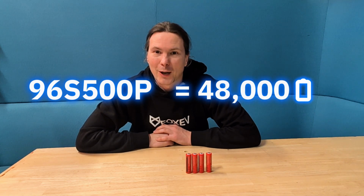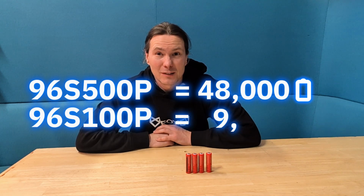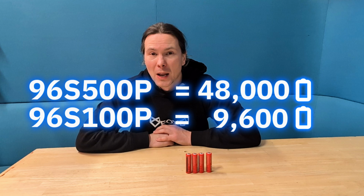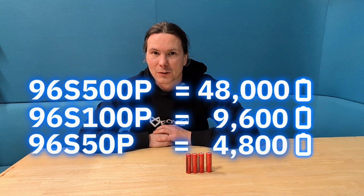400 volts, the motor, we also need to get to the 400 volts, so we need to put some of these batteries in series. So let's put 96 of these in series. So that gives us this notation here. 96S, 500P, that's 48,000 battery cells. 96S, 100P, that's 9,600 battery cells still. And 96S, 50P, that's 4,800 battery cells still.